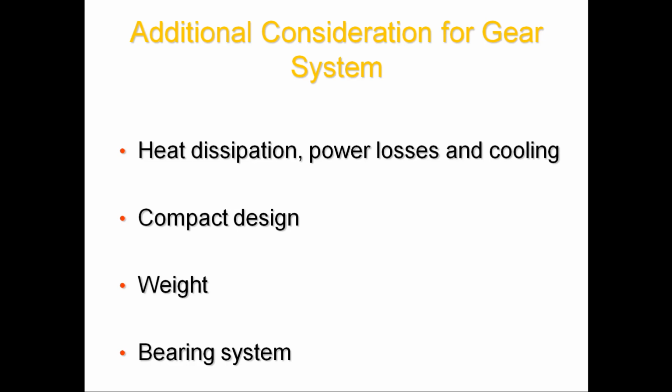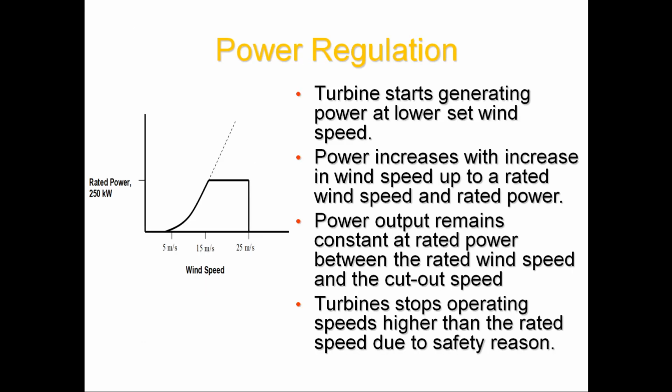It is very difficult if it stalls. So the bearing, lubrication, and heat dissipation should all be considered properly before designing a gear transmission system for a wind turbine.